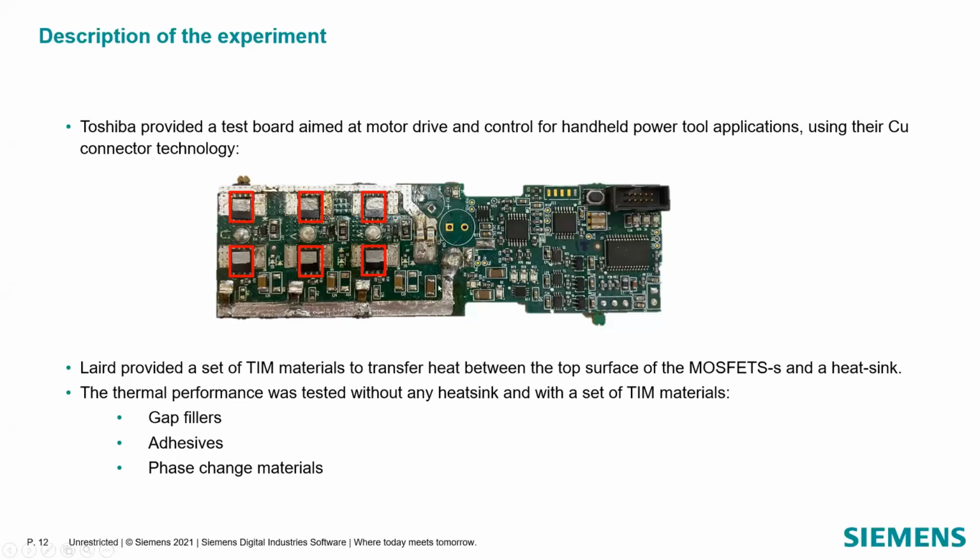This is the very same board Jürgis introduced before me. So it's a test board aimed at motor drive and control for handheld power tool applications. The components used are dual side cooled Toshiba MOSFETs. On one side, they are soldered on the board and cooled towards the PCB. And on the other side, either we won't cool them, we'll show that case, or we will add thermal interface materials provided by Laird on top of them and cool them through a heatsink. We use gap fillers, adhesives, and phase change materials from Laird for this purpose.